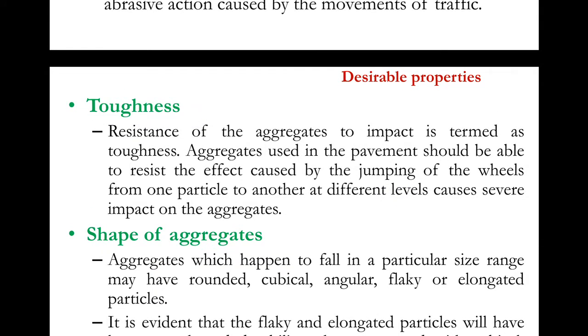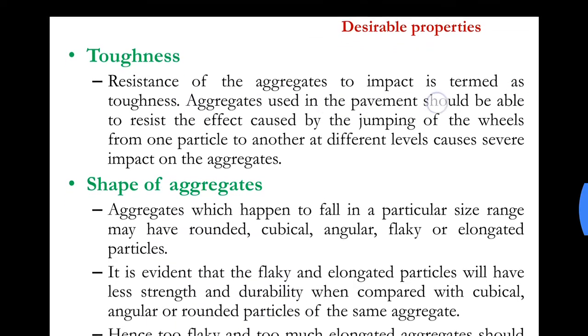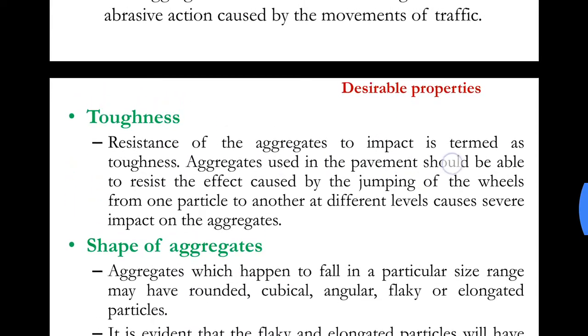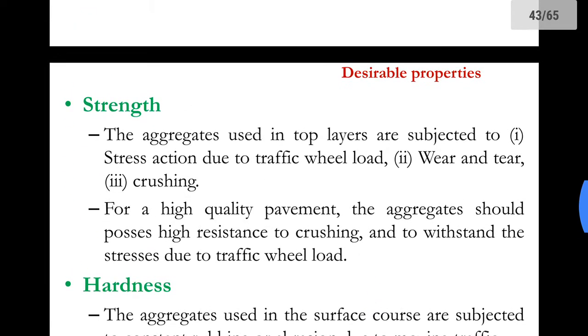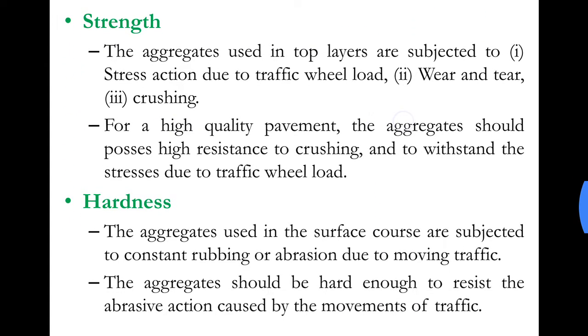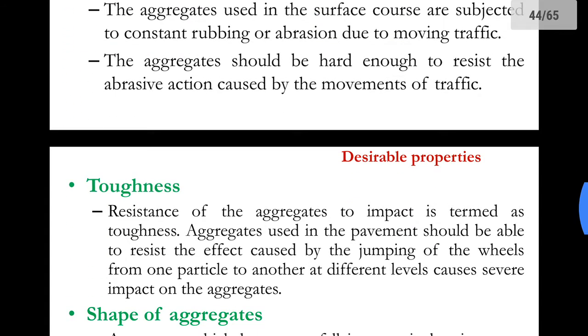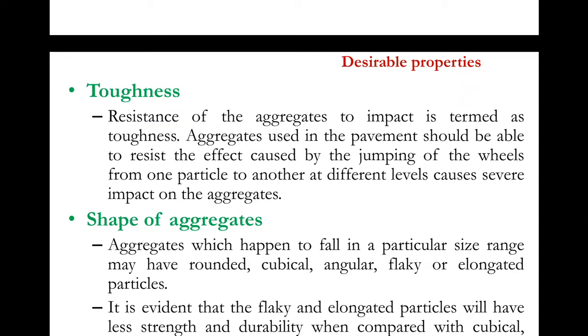The next property is toughness. The resistance of the aggregates to impact is termed as toughness. Okay, so impact is nothing but a sudden load. Okay, you need to note that in strength the type of load is a gradually applied load. Okay, and in the toughness the loading is impact loading or a sudden loading.